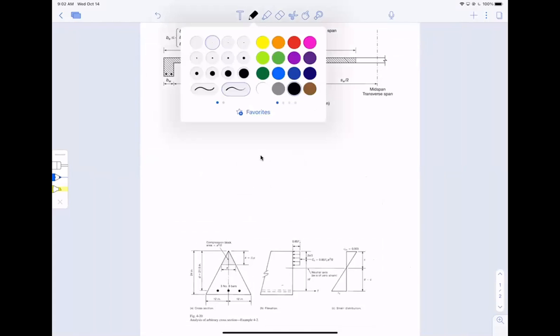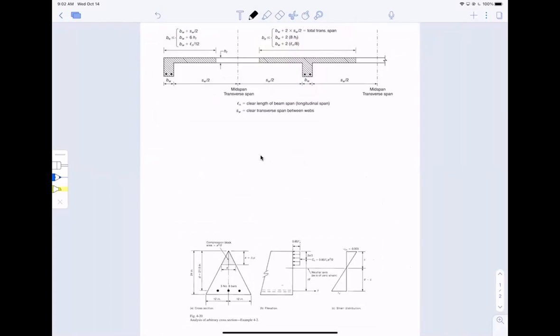This is the cross section you typically see from a joist or a slab beam, a T-beam integrated section. What it really looks like in the 3D view is something like this. I'm just trying to draw in a corner. Here I have an L-shaped beam, they call it a spandrel beam, or some people call it spandrel. And then I have a T-beam like this, and so on and so forth.